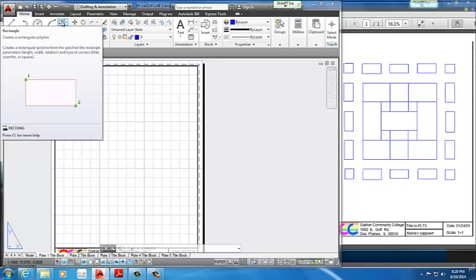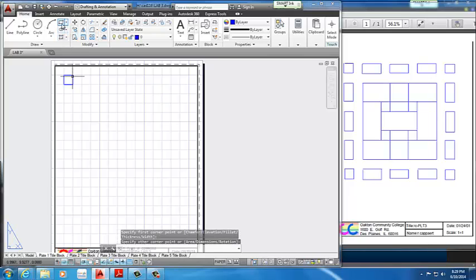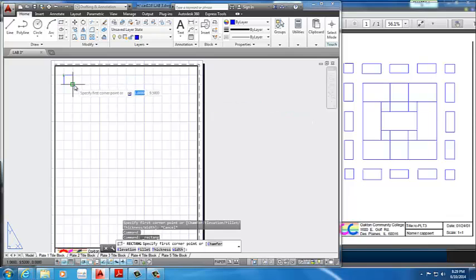So basically, for Lab 2, I will look over that drawing, and you create options of how I should design this. It's right here. Alright, so basically, I came up with an idea that looks like a rectangle. It looks like this is going to be my 1-inch length, and I'll work with that all the way around. Click on the rectangle command, and you can just create a box by selecting one end point where the center is. I know this is the center of the box.